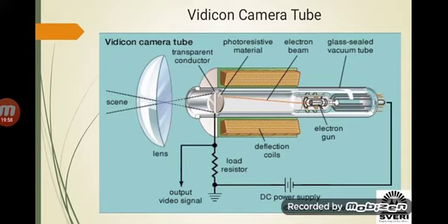And that is how, in scanning, we ensure that the electron gun covers the entire portion of that particular frame. For that you need to move from the left side to the right side, again start scanning with the next line and complete the line from left to right, and slowly it should scan horizontally, as well as the beam should keep moving down, so that it can complete the movement vertically as well.